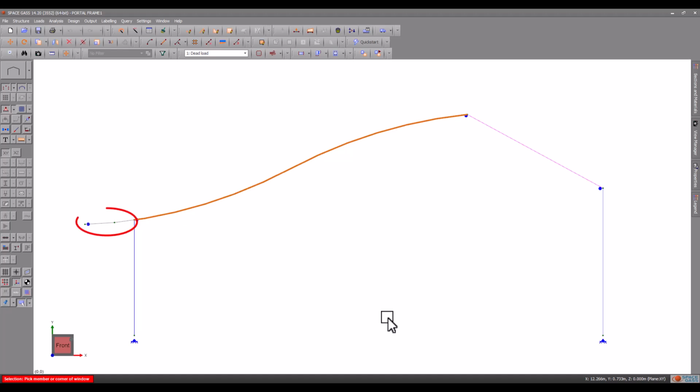Note that we are not including the cantilever, because the design rules for cantilevers are different to other members, and it must be dealt with separately. Note also that we must not extend a steel member over a major axis support for that member, and that is another reason why we can't include the cantilever with the curved rafter as a single steel member.